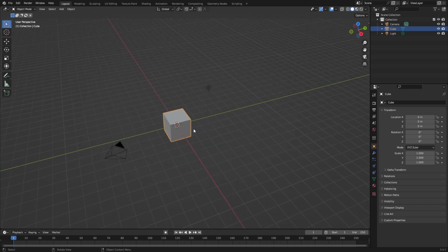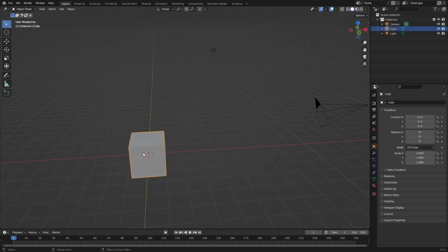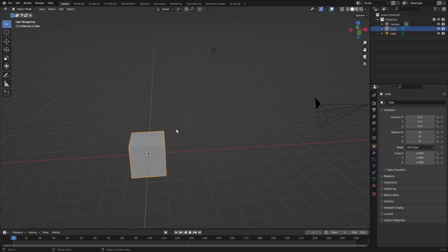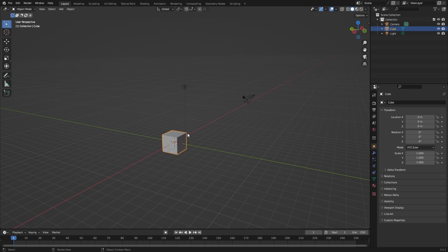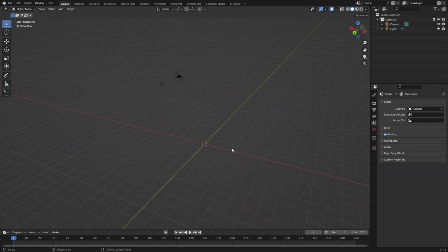So the first thing you want to do is, you'll see these things across here. You can see you can move stuff, rotate stuff, scale stuff, and all of them at once if you want to. But the thing I think every Blender user should do is learn to use hotkeys. So the hotkey for moving is G, the hotkey for rotating is R, and the hotkey for scaling is S. With that you can work a lot faster in Blender, and so that's what we'll be using today. I'll be telling you how else you can do it, but I'll be using hotkeys most of the time. And you can press X to delete stuff. So yes, delete the first cube by pressing X and deleting it.